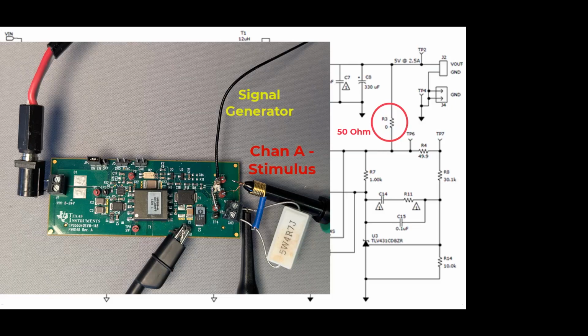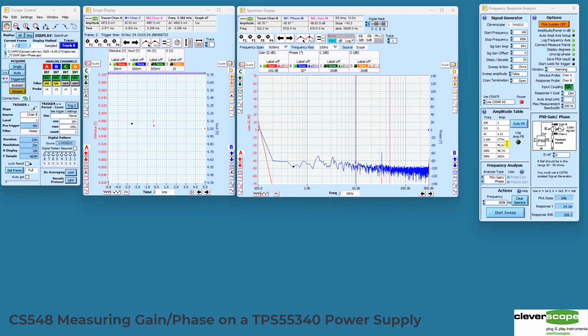Connect channel A, the stimulus, from 0 volts to TP6, the feedback resistor divider point. Connect channel B, the response, from 0 volts to V out, the output. Open and display the windows as you see here.